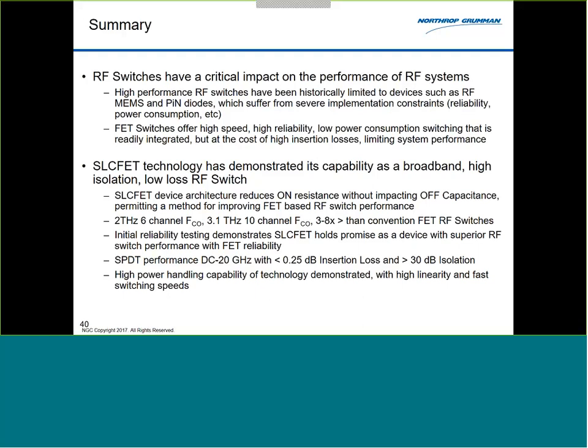That said, in terms of those surface states, oxygen contamination is something that you really do have to be aware of and make sure is taken care of. Surface preparation of your films and how you're handling your wafers during the processing sequences are all very critical to achieve the results that you want at the end of the day.